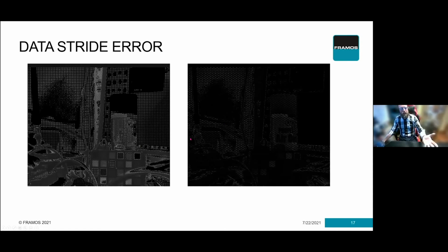Now, if you look at this, you can probably recognize there are some shapes here. There's a Macbeth chart, if you're familiar with the color checker, at the bottom. And what we're able to look at in this image is, first of all, there is some strange patterning here. That's actually a moire from a scaled Bayer pattern, but that's not the key. The key is that all the values are off. Everything's wrong.